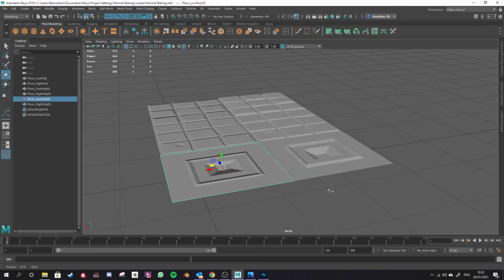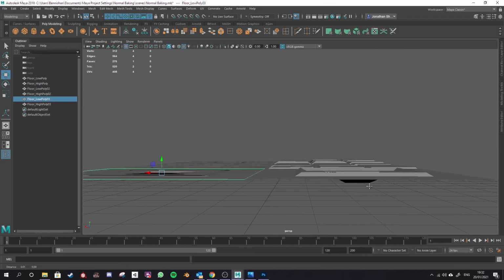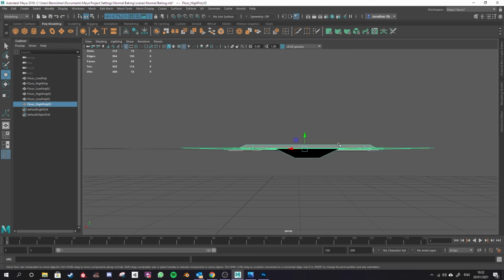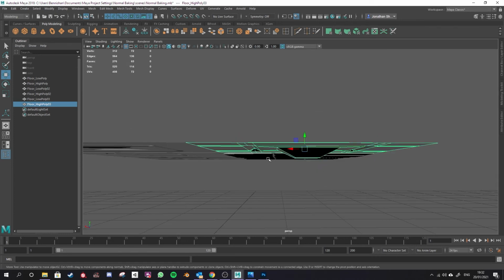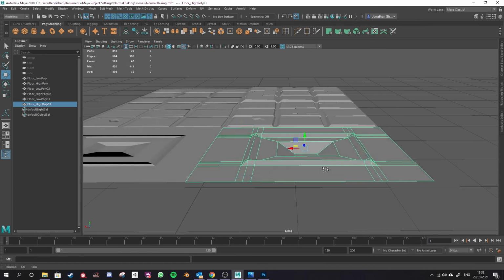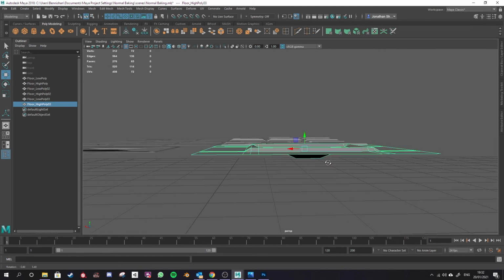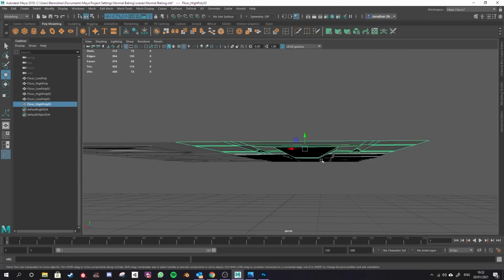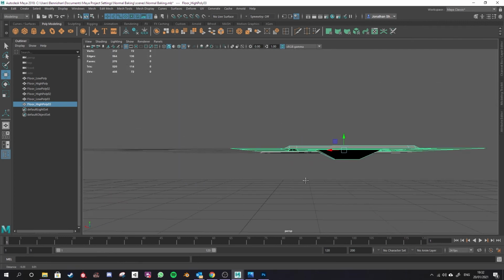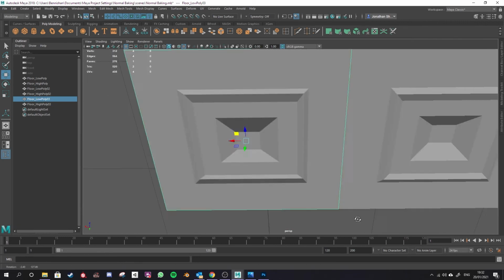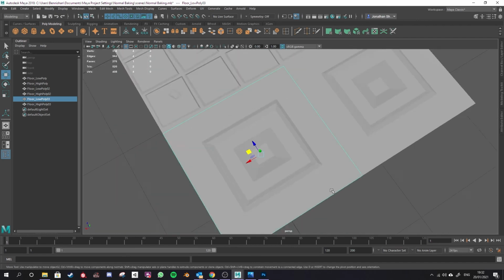Now, the reason that I included this example is because this is actually falling below the level of the geometry. So that was just to show you that the envelope can reach in underneath the faces to a certain degree, and you can use the settings in Maya to decide how deep you're going to go with that, in the envelope settings. But you can see I've depressed that down. This is completely flat, and yet I still get the impression of a sunken in object.